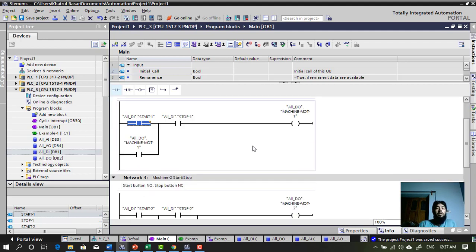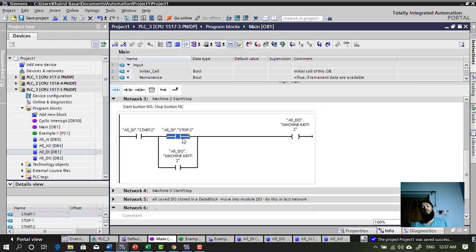Yes. So similarly for machine 2, we have a little thing to correct, as this one is here and this goes here. Start the button, stop is already connected, so 1 1 equal to 1, and when the operator releases this, because this output is this one, this bit is already previously turned on by turning on the push button, so it will be kept on through this side. This will be on, this is on, and this will remain on unless and until someone presses the stop button or power goes off.